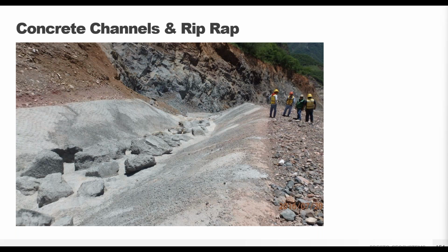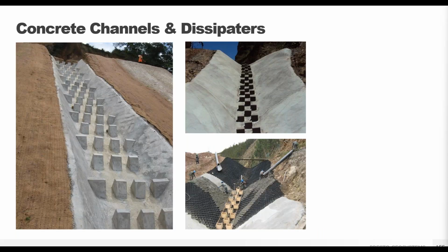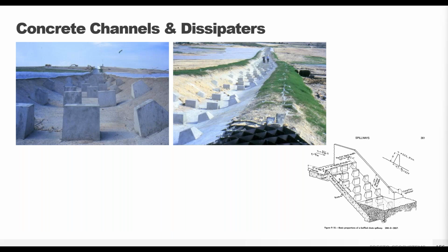The GeoWeb channel system is flexible enough to modify the structure. Here's a technique tip of grouting in large riprap in a rockfall area of a mine closure channel. Or you can add energy dissipators, again, directly to your GeoWeb with concrete infill, and directly as part of your channel design.